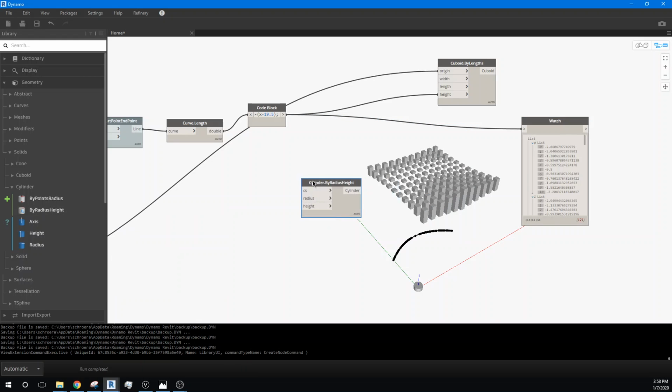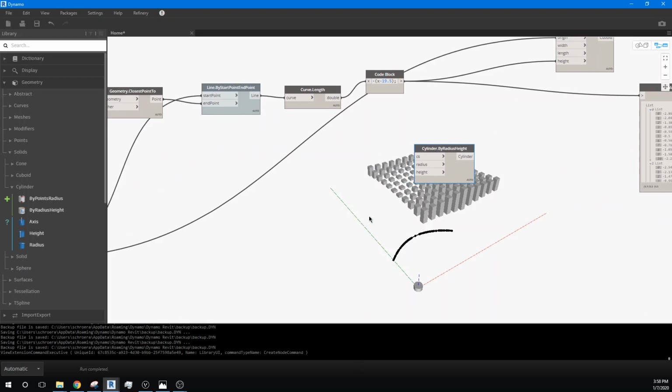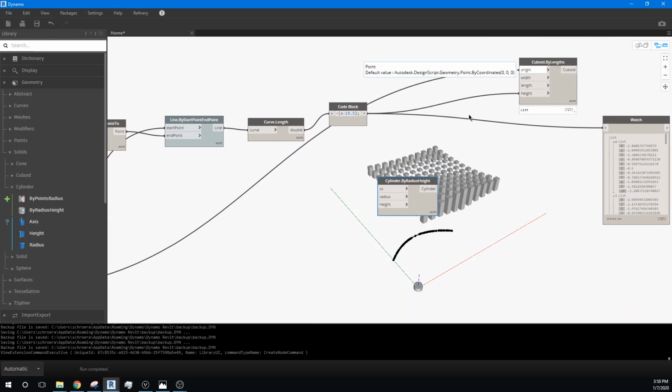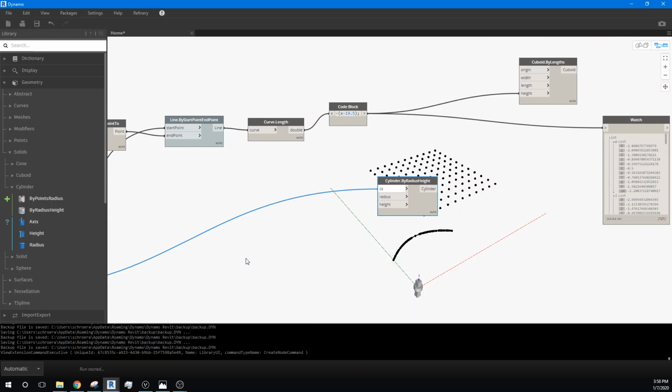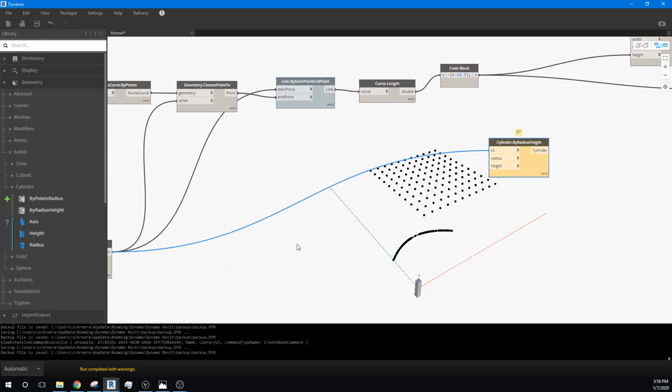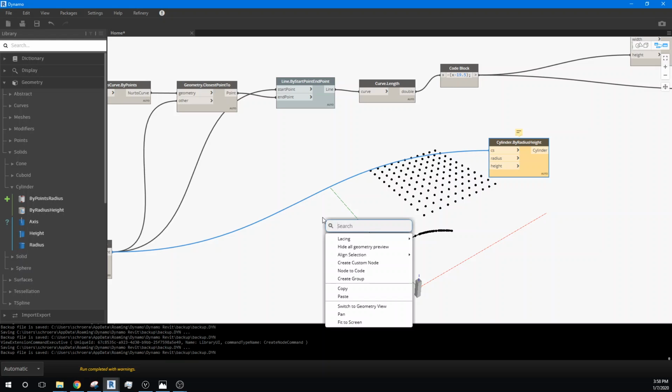You'll notice that once I brought it onto the screen, I get a cylinder, but I need a coordinate system, because if I feed the origin into it, it's going to reject it. Even though those are defined as points, it's not defined well enough for this function to actually work. So we need to transfer the idea of these points into what is a unique coordinate system for each point. So let's search for something that will allow us to do that.